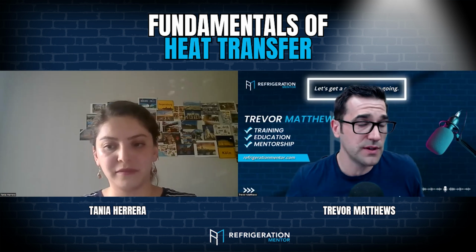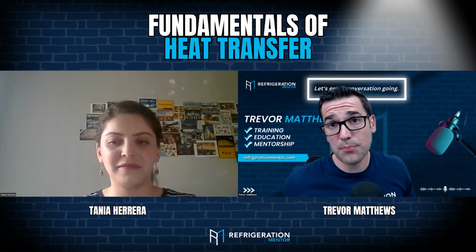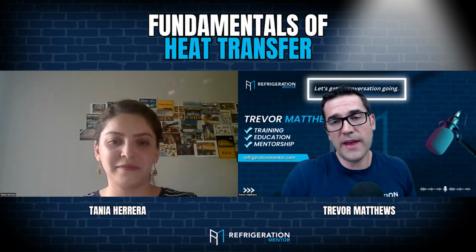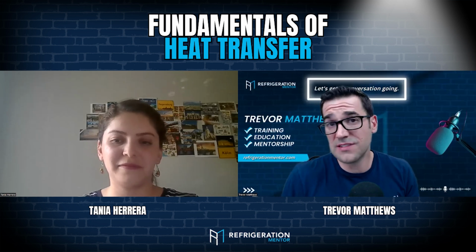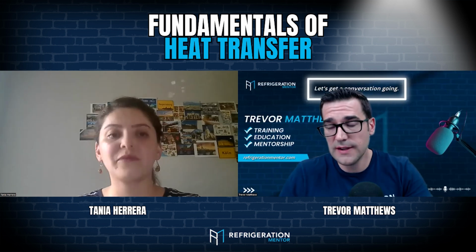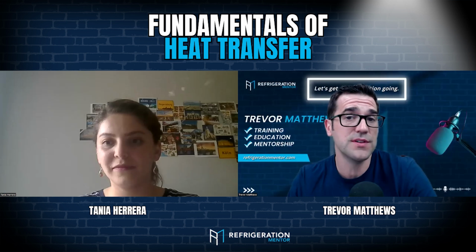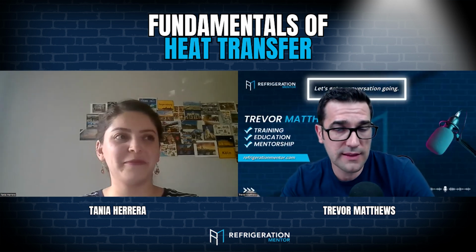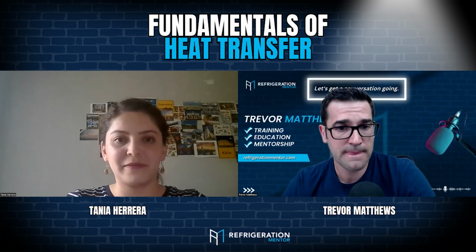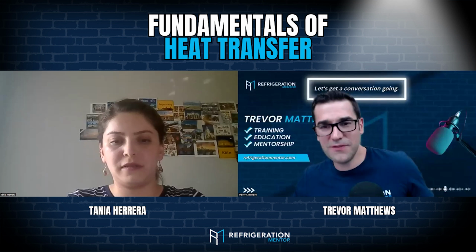Like we talked about with Will last week, and I highly recommend you go watch that one, that control system that Guntner designed is going to help that system stay in subcritical for more time of the year. And that's where that heat transfer comes into effect, and you get better heat transfer at that point, because you're getting both latent and sensible versus just sensible when you're in transcritical, correct? Yes, I agree. That's correct. I agree. I love that.